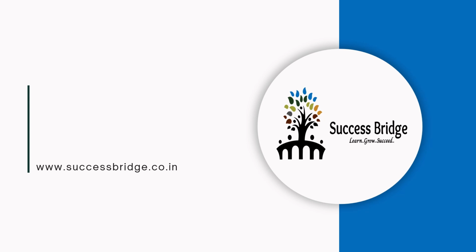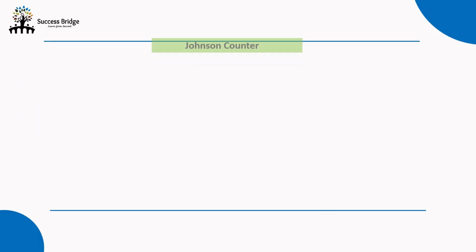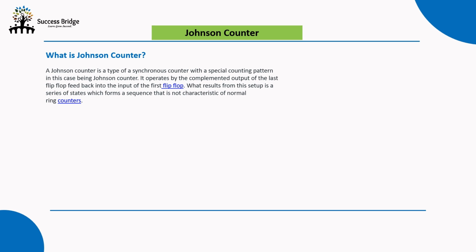Today we are discussing Johnson's counter. Before starting our explanation, let's see what a Johnson counter is. A Johnson counter is a modified ring counter in which the output from the last flip-flop is inverted and fed back as an input to the first. It is called an inverse feedback counter or twisted ring counter.